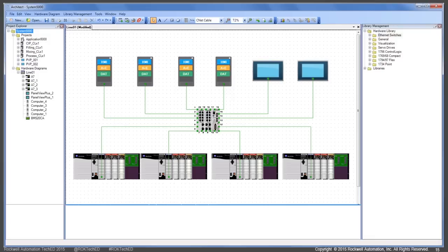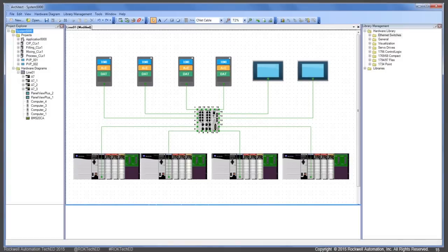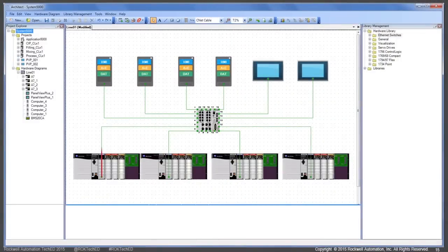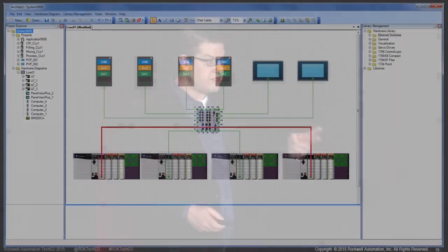2 examples of these opportunities are setting up runtime communications. So now you can connect your RSLinx Enterprise data server to your ControlLogix to set up your shortcuts. So what you would do is you take your Ethernet module and your controller from the rack and drag it onto your data server. This sets up the path between the 2, as well as designate your targeted shortcut. We could also set up interprocessor communications. So we could go between 2 chassis and set up communications for produce consume tags. So again, these are just 2 examples of what you can do now with the system layout.